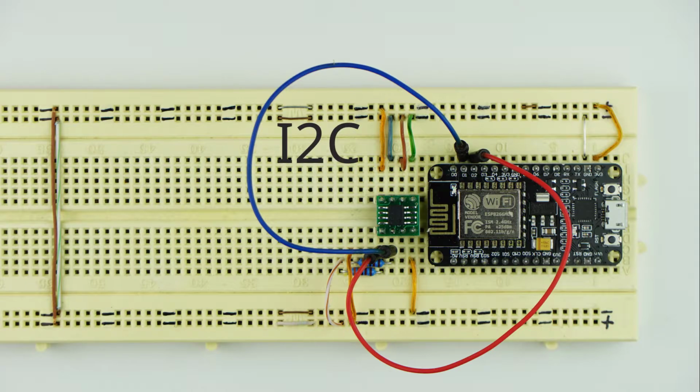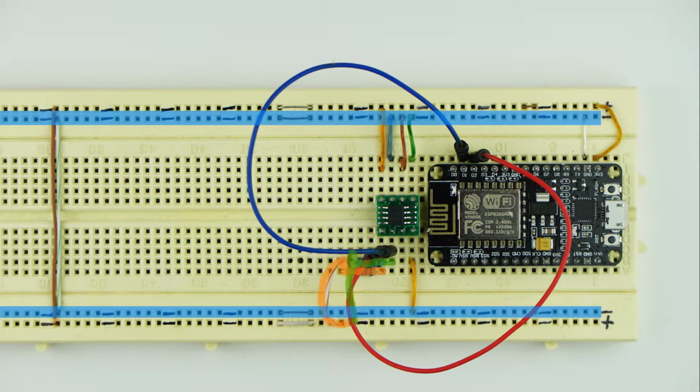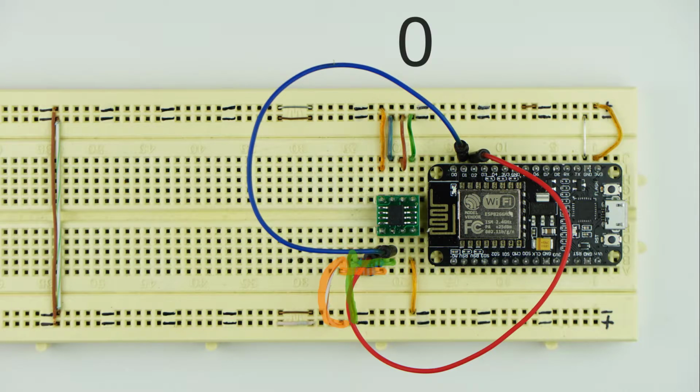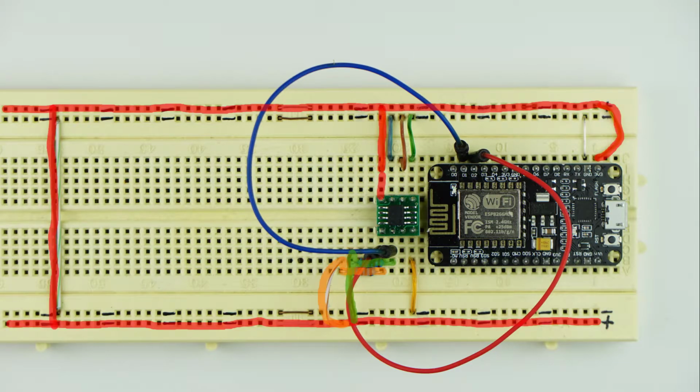Because the I2C interface only knows how to bring the clock and data buses to the ground, we need to add so-called pull-up resistors so as to pull the buses back to the plus. This way the buses can have a 0 state when grounded and a 1 state when connected to a positive power supply. And please make sure you connect everything to the same power supply so you don't accidentally fry the CPU, and to have a reliable communication on the I2C bus.